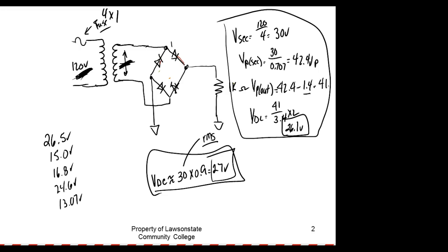And that means, okay, what would I get if I put 24 volts on that? Well, I'd get 6 volts out, right? Y'all understand that? So sometimes transformers don't give you the division ratio. They give you an input voltage, and they give you an output voltage, right? And then you can calculate the turns ratio. And then if you know the turns ratio of the transformer, you can hook it up to anything you want. And then you get what you need out. And this happens sometimes. So this is a full wave bridge.